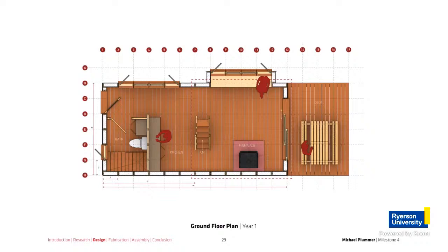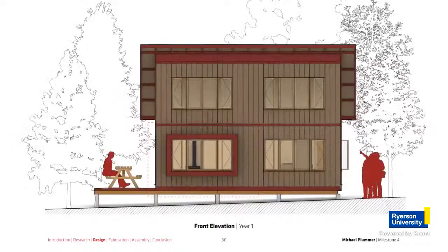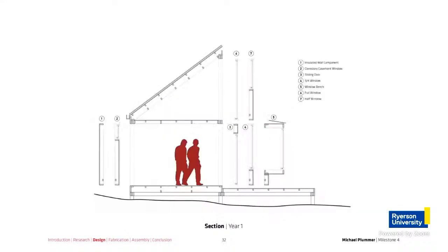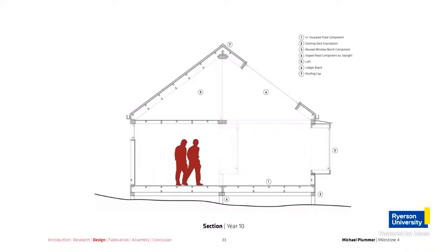The supports are made up of 6 floor components, 4 corner assemblies, and 4 wood lintels that span each opening. This allows for a high degree of flexibility within each of the 4 sides. This flexibility allows for a variety of infill options, such as exterior walls with windows, doors, or solid, or one large opening to gain access to adjoining 12 by 12 foot module. The lintels are adequately sized to accommodate a floor above, providing the opportunity to expand the system in the Z direction without conflicting with the infill below.